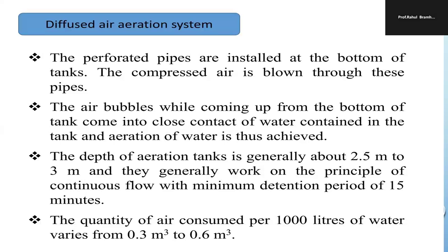In this method, the perforated pipes are installed at the bottom of the tank, and with the help of a compressor we provide air through those perforated pipes.